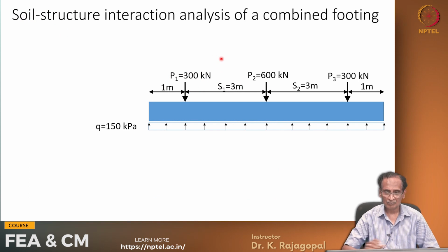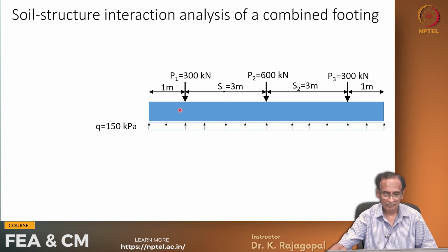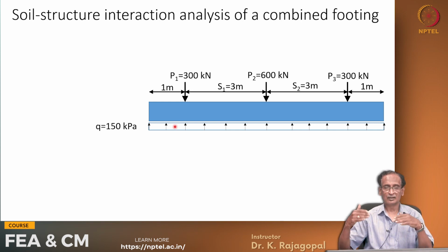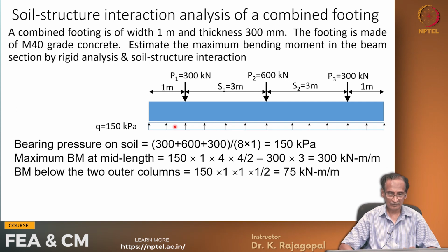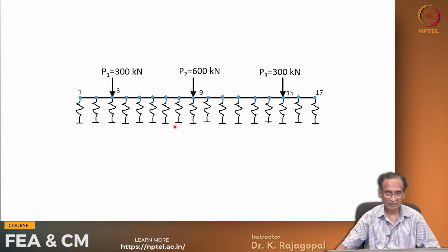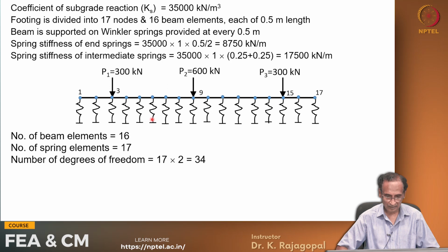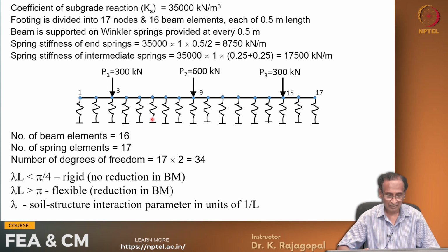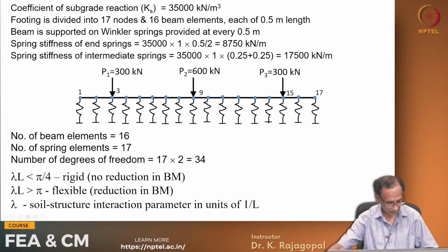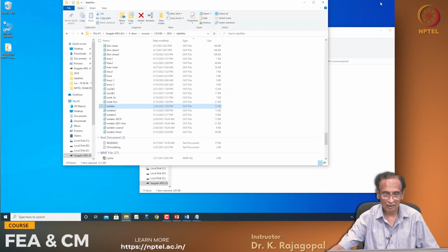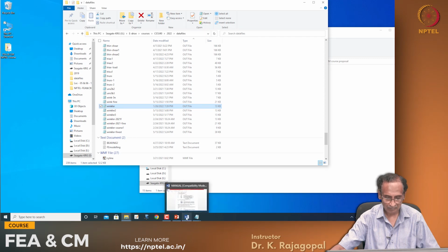Then the other one is the combined footing supported on soil, and the soil itself is modeled using Winkler springs. Okay, let me show you the finite element equivalent. So here we have this beam, and it is supported on a series of springs, and this is the loading that we have given. Okay, and so we get different solutions, and we will try to see how we can do this in the finite element program.